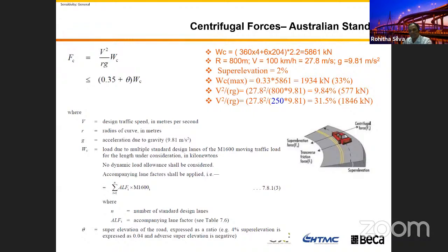Yeah, you can easily calculate the tensile stress at the bottom of your cross section, and people do this stress analysis using the deflection. They got this correlation and it works out to be roughly L over 360. But when we design a bridge, we can't design it to crack. So you need to make sure you articulate the bridge to absorb that differential settlement.